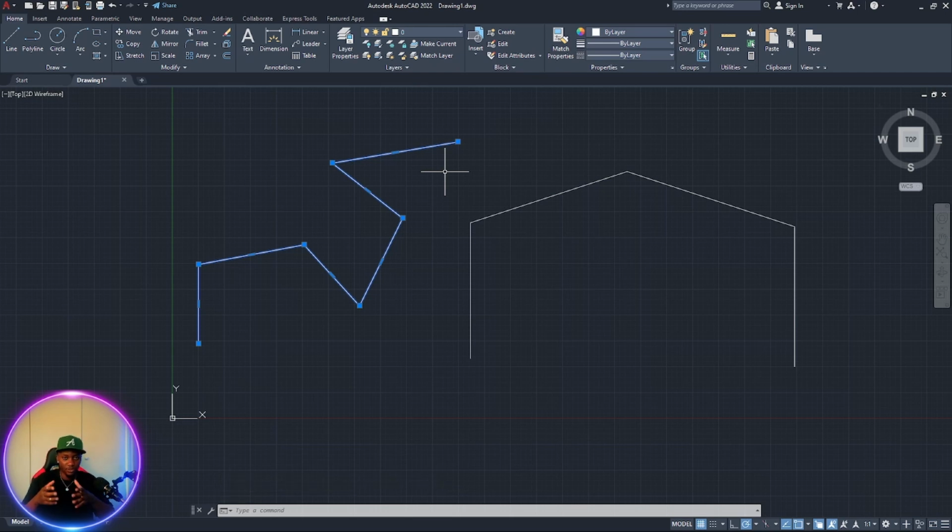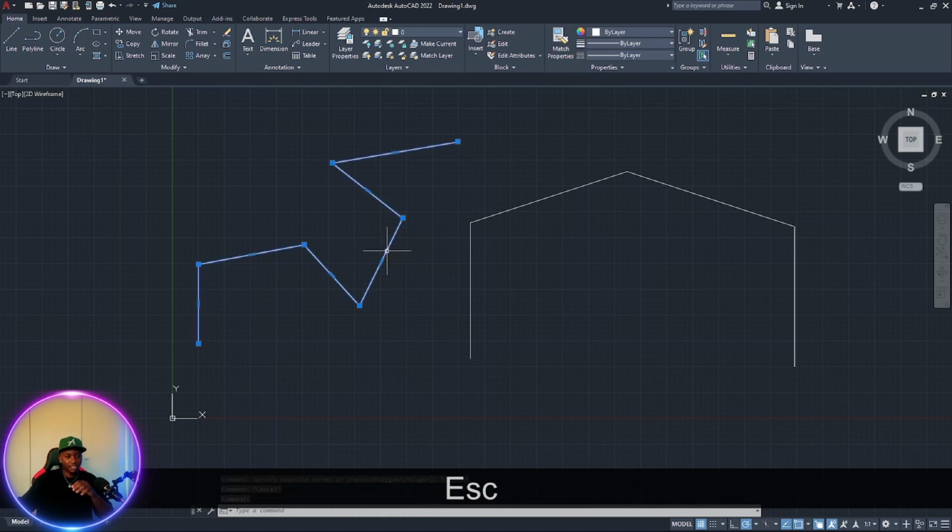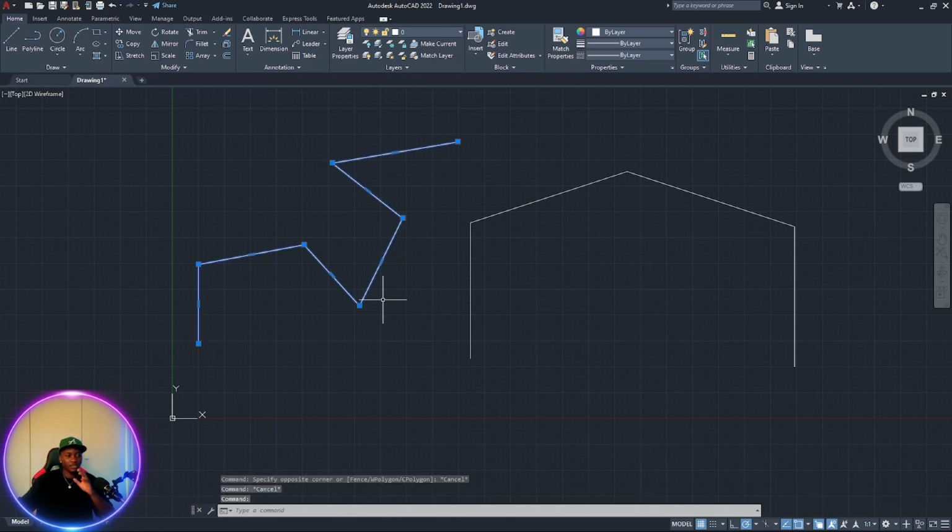As I'm clicking this line right here, it records that it starts from here to this side. With a polyline, if I click anything right here, it selects every line. So that's the thing with polyline. A line is single, while with a polyline, everything that's attached to the object that you clicked is gonna be selected.